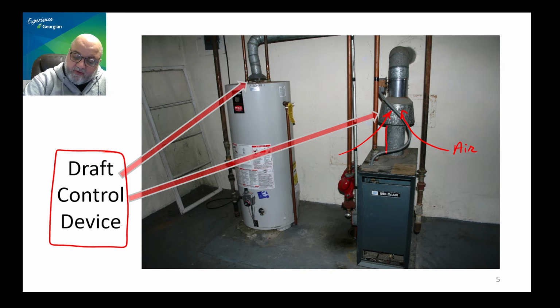So the combustion products, if you look at the stack here, are very, very hot in here. They are at their highest temperature condition right now. But when they are mixed with air, they become rather cooler, and they are safer. First of all, they are safer to be conducted through the venting system. And secondly, that air movement, we call this dilution air by definition, and it is diluting the combustion products basically.